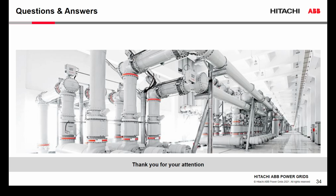Either the monitoring systems can be interconnected based on the IEC 61850 protocol or the DNP3 protocol, but that is not really a code. That is the protocol for the interconnection to the SCADA system. Other than that, I would not know any requirement which requires a monitoring system.